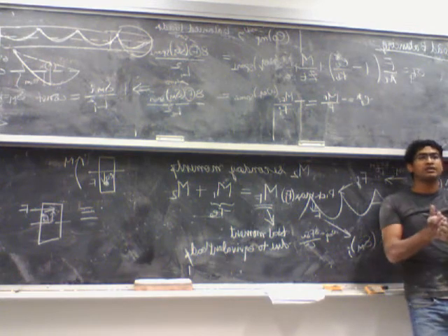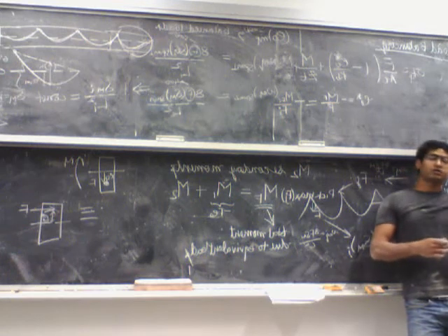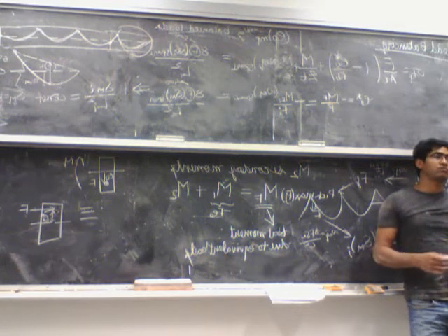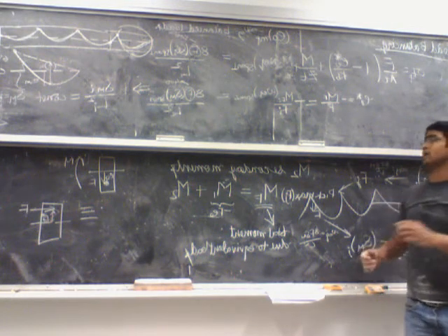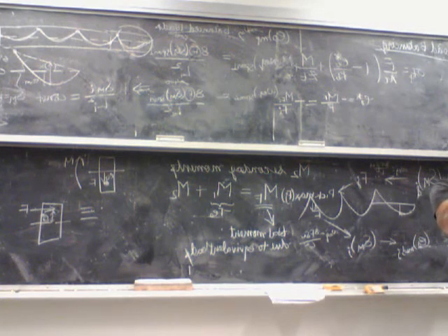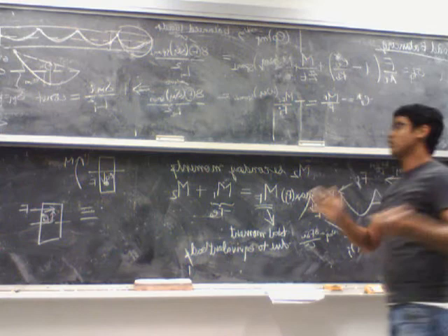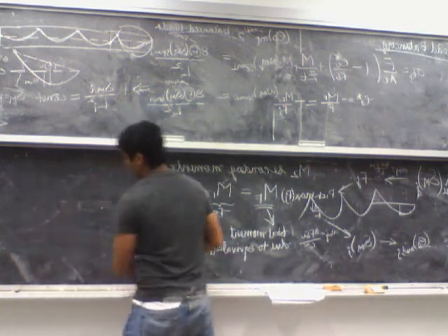And once you have the eccentricity at the midspan, you can actually define the entire profile. Just go ahead and run the tendon profile using the parabolic equations. That's exactly what you said. Yeah, so when I mentioned that, once you define the tendon profile, you need to find out what is the maximum E naught in the entire span. So in order to find out the maximum E naught, you need to find out the equation for the tendon.